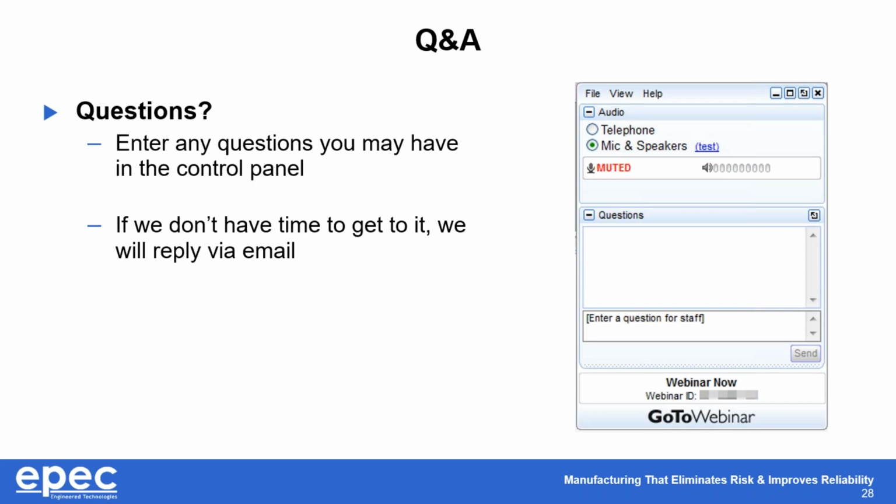We'll see high temperature, or HT, polyimide based adhesive Coverlays. Those operate at a 200 degrees Celsius continuous operating temperature, a very specialized material. Or there's a TK material, which is a Teflon polyimide hybrid. That's a high-speed material, as the name says, used for high-speed applications.